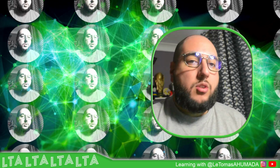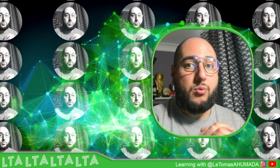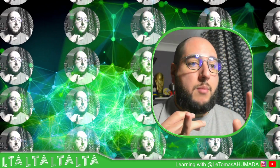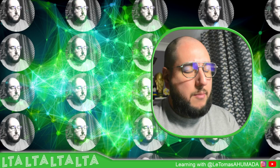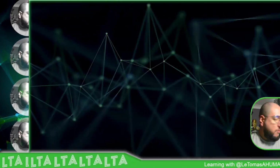In this video, what we're going to see are the function blocks related to the SMTP. So basically, SMTP is Simple Mail Transfer Protocol, okay? And basically, if we want to send an email from the Modicon M172, we just need to use those function blocks in order to send the email. So in the previous video, we have seen the DNS function blocks. Once we have selected the SMTP server, we just need to get the domain, and that domain will be converted into IP address format that will then be used in the function block that we're going to see today. So let's go to the software.